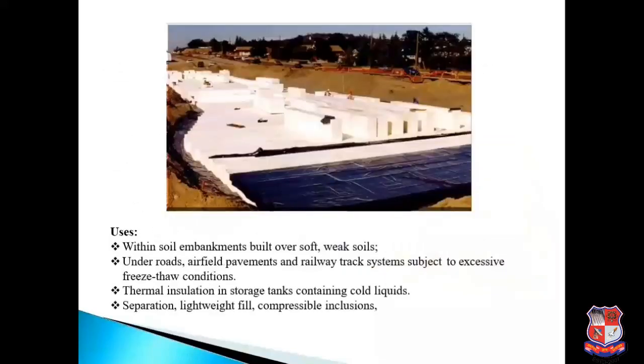So uses are with soil embankments built over soft or weak soil, under road, airfield pavements and railway track systems subjected to excessive freeze-thaw conditions, thermal insulation in storage tanks containing cold liquids, separation, lightweight filling, compressible inclusions.